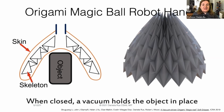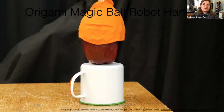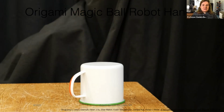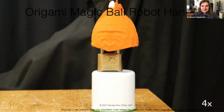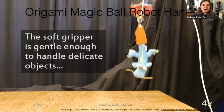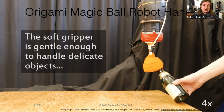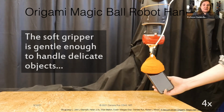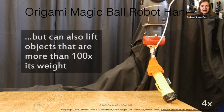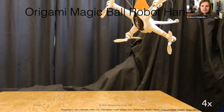And here you can see an example of using origami as a skeleton inside a soft body. And it turns out that by doing this, by taking a soft body and incorporating an origami structure in it, we can generate very high payload for the robot. In fact, this gripper that is shaped like a tulip, a non-traditional gripper, has the ability to lift hundreds of times its weight. For example, we can have a linear actuator that weighs 3 grams, and that linear actuator will be able to lift up to 3 kilograms.